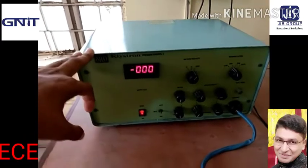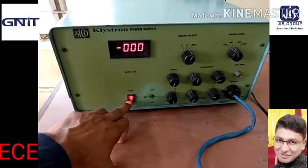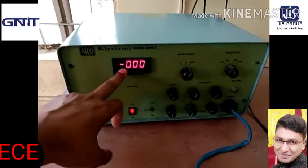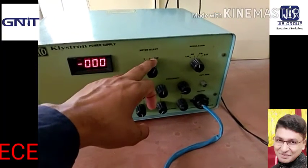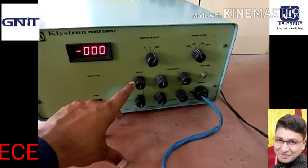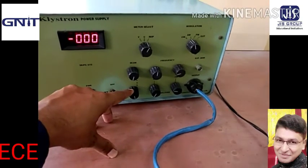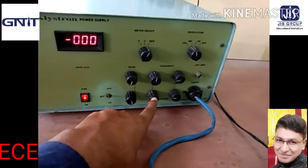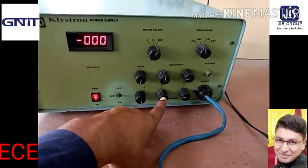This is our Klystron power supply. Power on switch, AST switch, meter display, meter selector. This is repeller, beam current and beam voltage. This knob varies beam voltage or beam current. This knob varies repeller voltage. These two knobs are for amplitude modulation. This is for frequency, this is for amplitude.